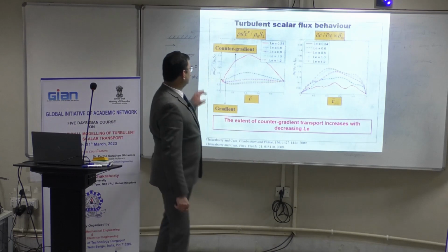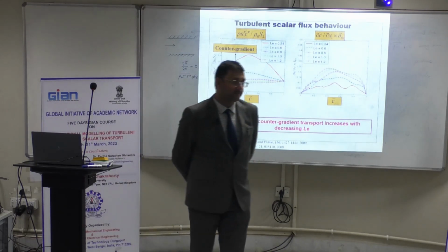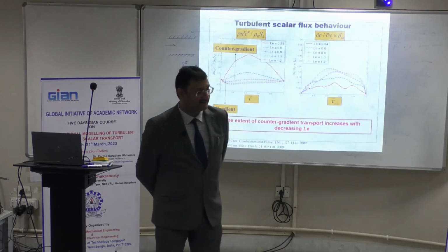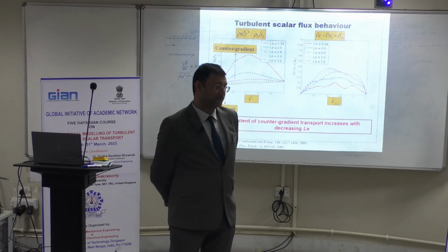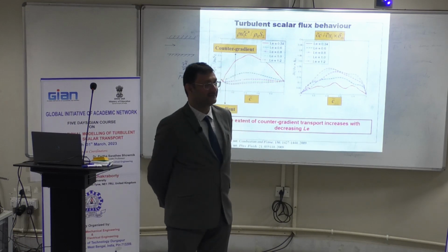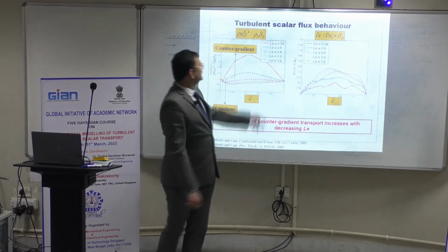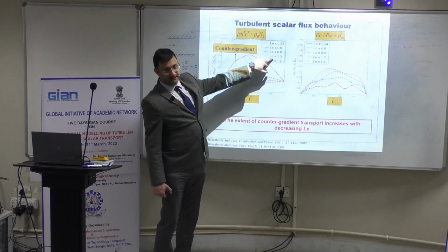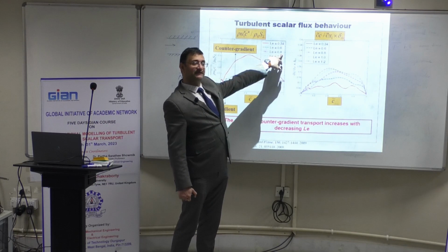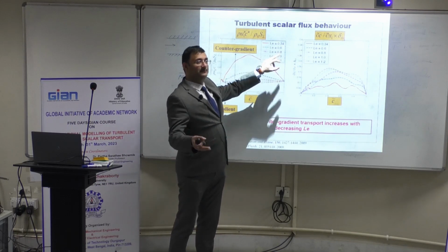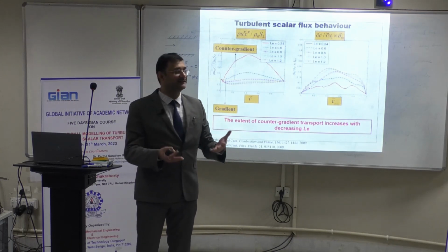The unburned gas turbulence is exactly the same for all of these cases. So the flame towards the unburned gas side is seeing exactly the same turbulence. But what happens within the flame is drastically different, as you can see. Physical significance, as I said: stoichiometric methane air. You put hydrogen blending, 20% hydrogen with methane. Methane is a good representation of natural gas.